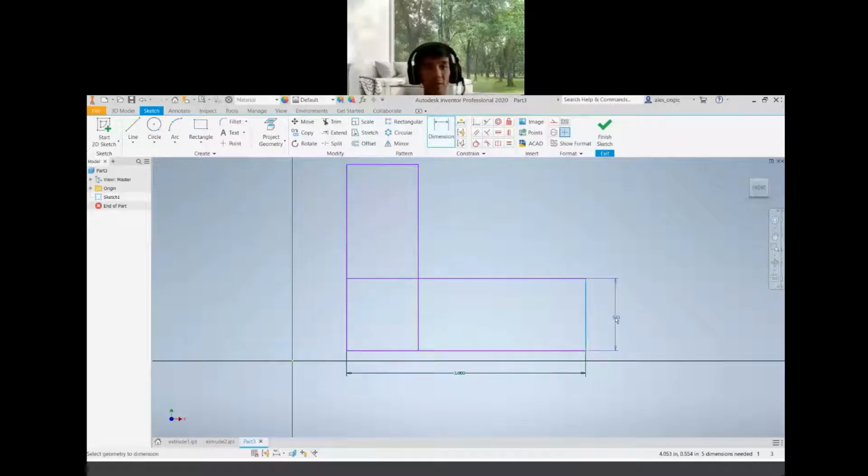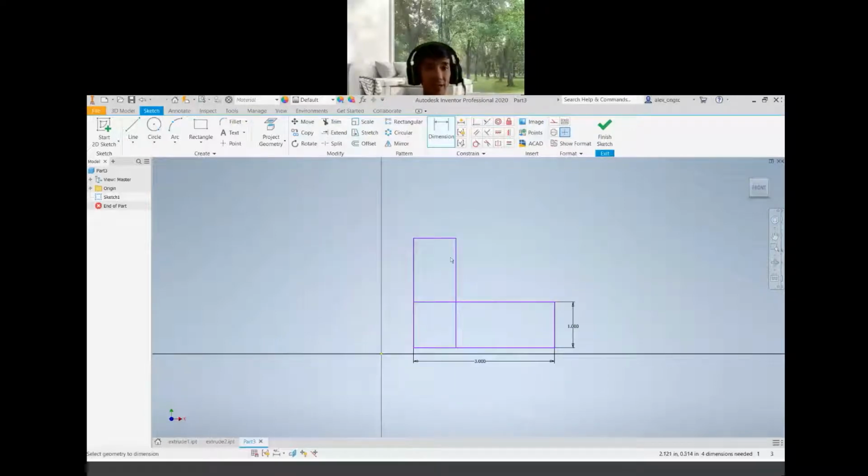So we are going to perform extrude again. Okay, you will see now, once we go to extrude, since you have more than one profile. Profile means sketching here. So you need to define your profile, that means you select your profile. You can see this one can be one profile, one here.